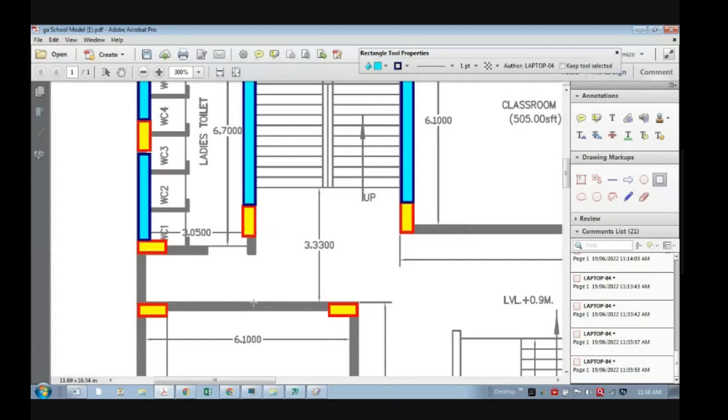So I will provide one beam over here. ऐसे कुछ तो beam rest. Okay. And once I have this main beam with me, then I can rest this horizontal beam on that beam. So we can rest the beams on beam also. Not necessary that beam should be on the column, it should be on the beams also. So I can provide like this also. Better solution is always resting beams on columns, but in such cases there is no other choice.